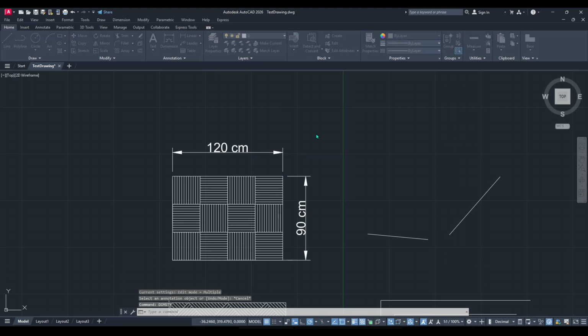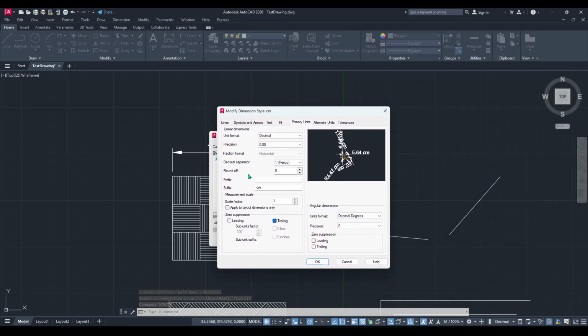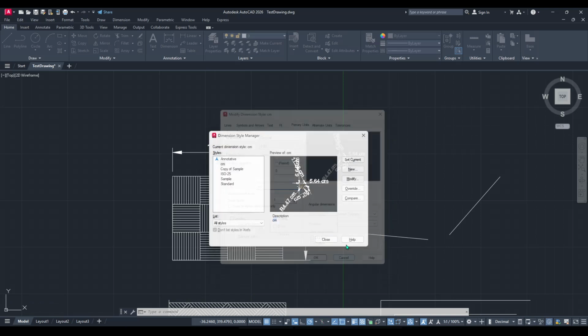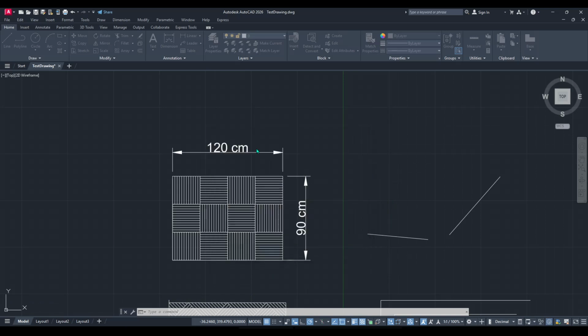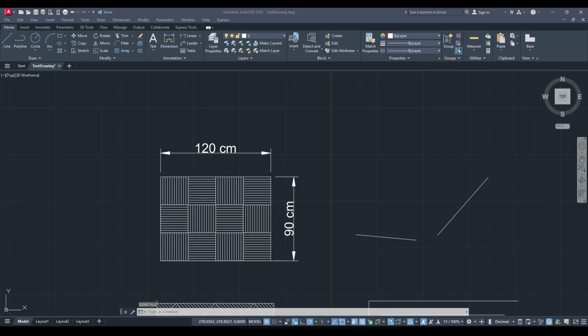To recap the essentials, open your drawing, type units, press enter, and change the insertion scale to meters. Remember, this setting doesn't rescale existing geometry. You'll handle any needed conversion by scaling your drawing manually based on its original unit. That's all you need to set units to meters in AutoCAD. Keep your insertion scale in meters, verify your source units, and you'll maintain accurate, consistent drawings.